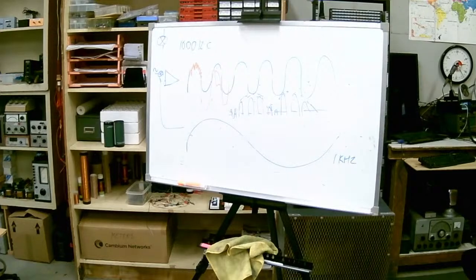Okay. So if I expand this out, I can see the carrier. There's your carrier, and there's your audio on top of that. Those carriers are getting bigger and smaller. So expand it out, that's the carrier frequency. Then we're looking at just this part right here. Well, it's the average. It's modulated all the time. So if you just went to the middle there, 970 kilohertz.